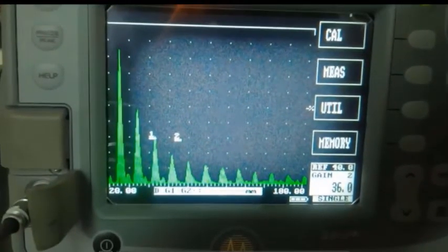All right, so we are all set now to collect the echoes from a known sample thickness, and this is what you can see from here, these are basically the back wall signals. There are multiple back wall signals. We have chosen the range or the scale on the x-axis in such a manner that multiple back walls will appear on the display.